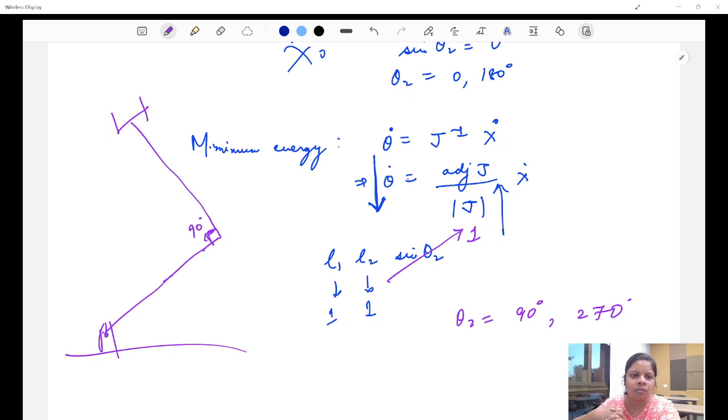Let's say right now the task is just that I have to stretch my hand and move it in a circular way. The other joint that I have, where theta 2 is 0, becomes redundant. I don't need it to do that. So for a redundant manipulator, you have more degrees of freedom than required to do the task. And then I think it was covered: then you have the concept of pseudo inverse. I told you how to find it also. The other way of calculation is you find out J transpose, multiply it with J, and it's a formula.